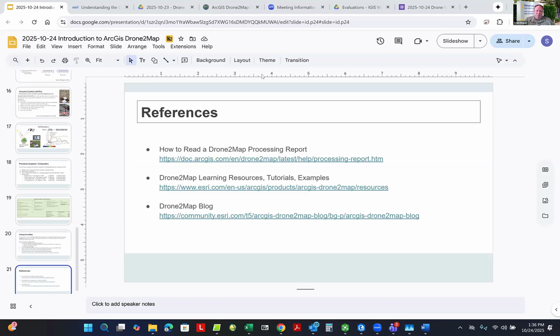Instead of looking straight down at nadir, you can set it to like a 65% angle and then fly in that double grid pattern or the hatch pattern, so you get a lot of different view angles on the sides of objects for much, much more robust elevation modeling in your products.